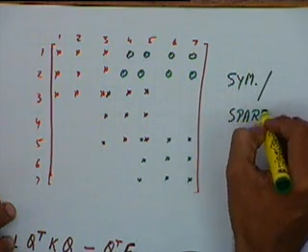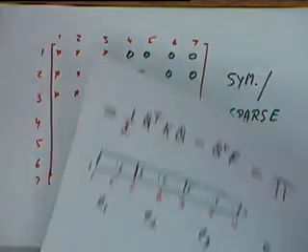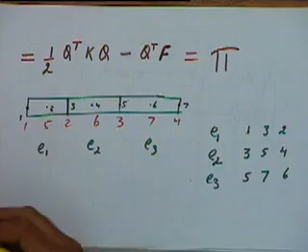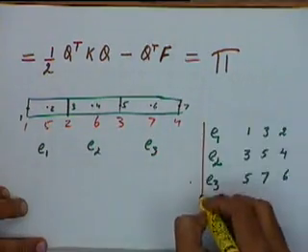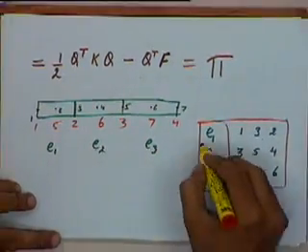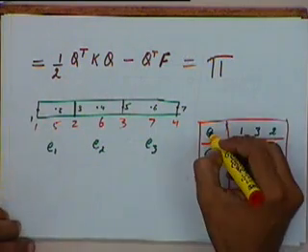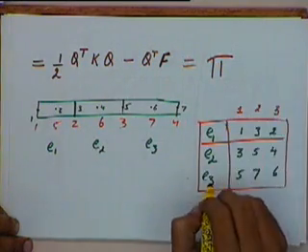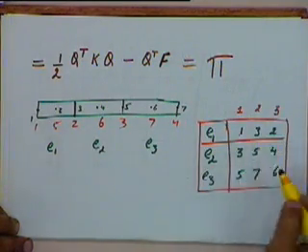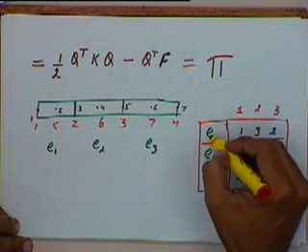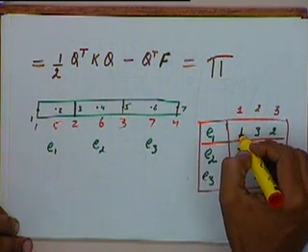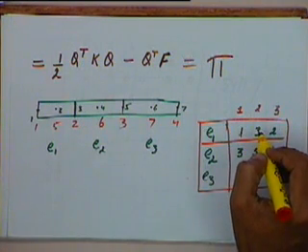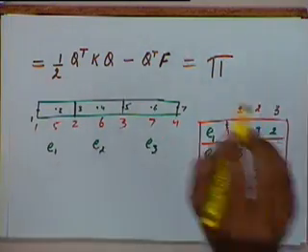So how does the local numbering 1, 3, 2 make a difference here? In this table, what I am basically saying is that for each element, the local numbers 1, 2 and 3 correspond to global numbers 1, 3 and 2. The local number 1 for this node is global node number 1. So what difference will it make had the local node numbering been 1, 2, 3, had the local numbering been in a sequence?